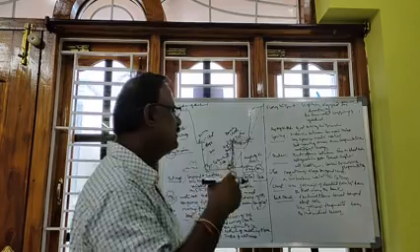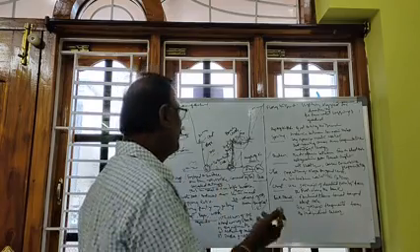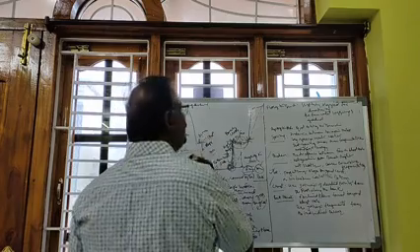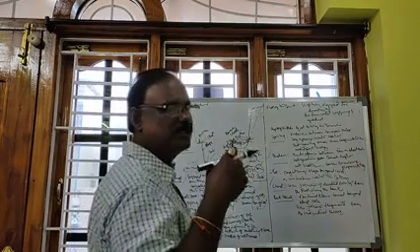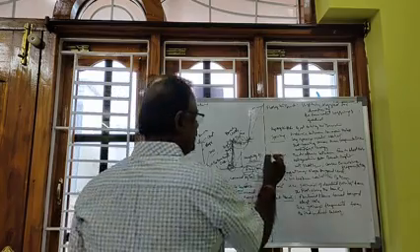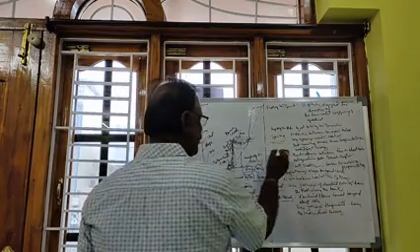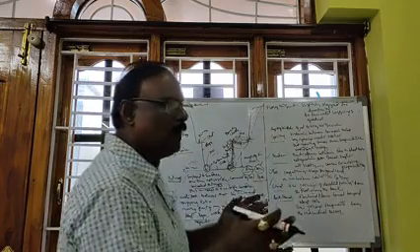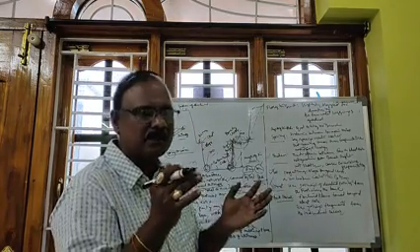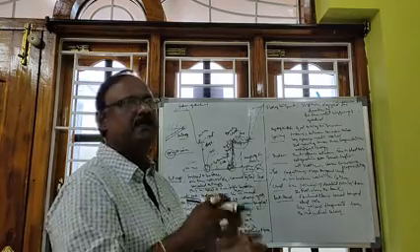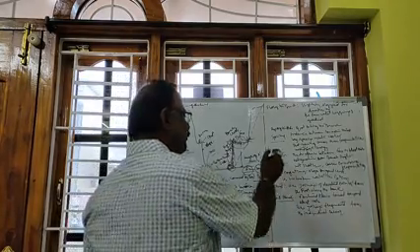If the distance is very much greater, a crater is formed and unblasted rock is formed. When the burden is more, unfractured rock remains.